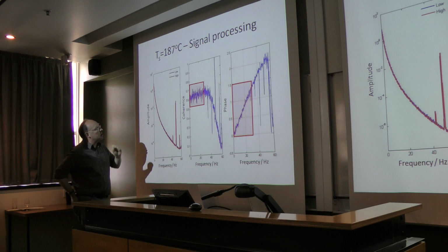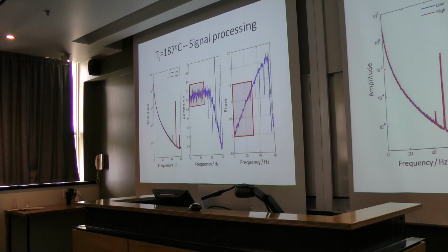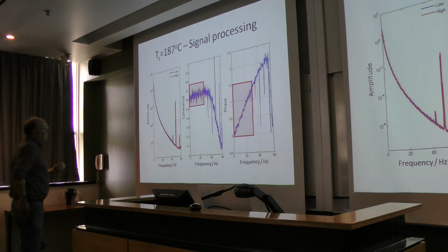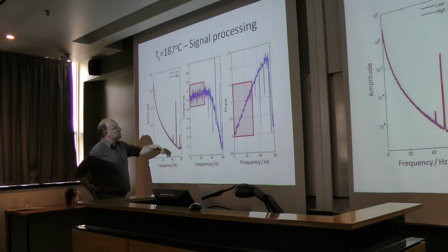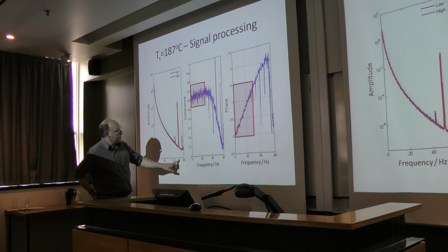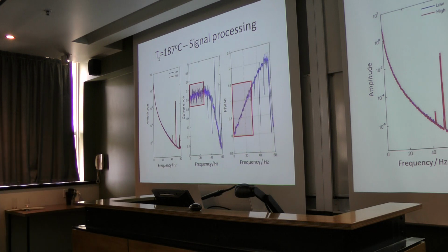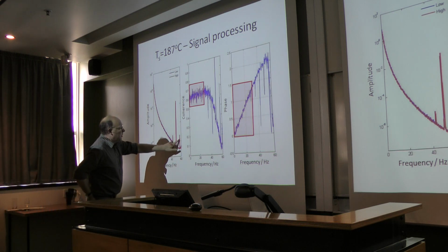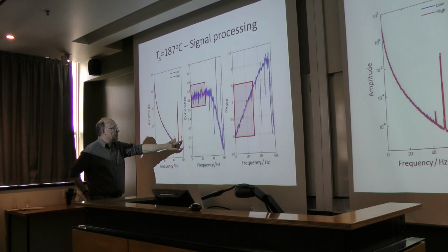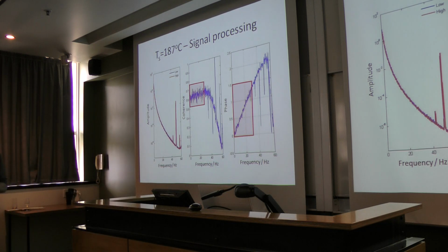Really, this is here to show us that the two time series, although they look chaotic, I suppose they are chaotic, they're turbulent, are giving very similar Fourier transforms. What that is all about is actually an anomaly. That's at 50 Hertz, so the thermocouples are picking up on the AC power supply. I'm not sure what these others are all about. It's been suggested to me that they're to do with the thermocouple leads acting like aerials, but I don't know.